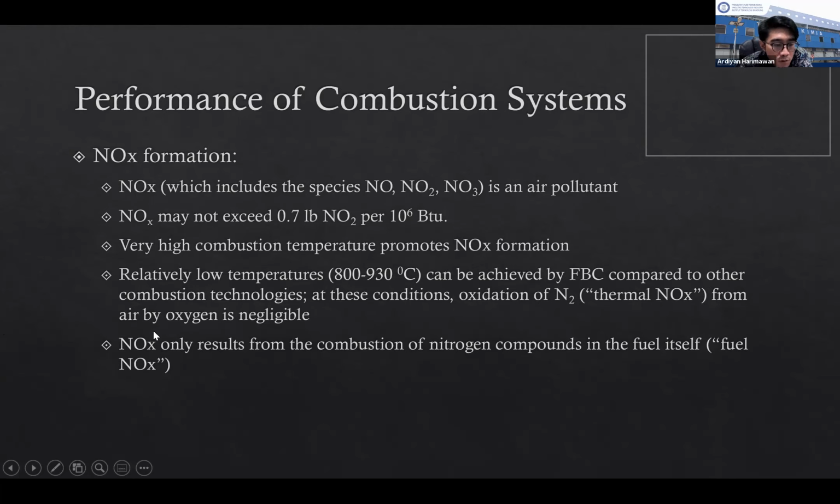It can be NOx, but only result from the combustion of nitrogen compounds in the fuel itself. So maybe the coal or the biomass, if you are using biomass for the combustion, it will contain nitrogen compounds. So if you do the combustion at low temperature, you might find NOx, but it's called fuel NOx. Fuel NOx is NOx from nitrogen in the fuel, while thermal NOx comes from the nitrogen in the air.